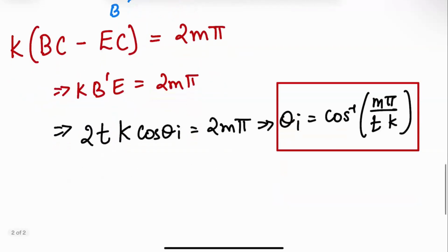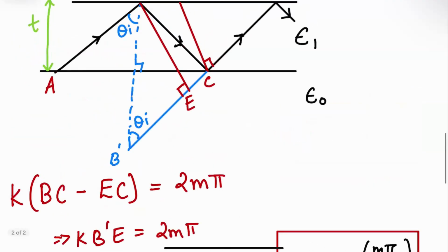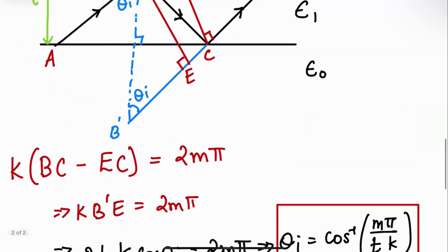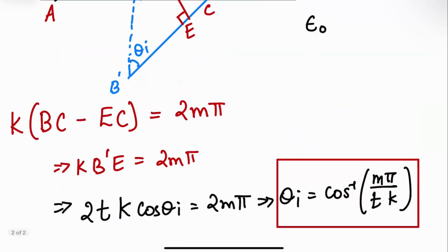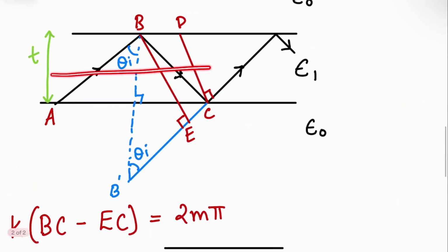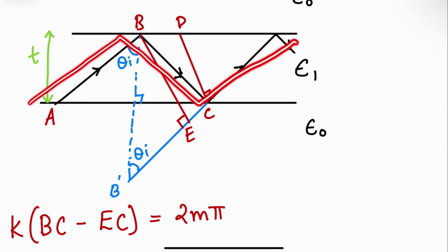So what is this saying? This is saying that the incidence angles at which I can satisfy that phase relationship, where this point is a phase advance from here or a ray advance from here, only happen at certain angles. So only these angles can support a plane wave propagation in this waveguide. If I come in at this angle, then it satisfies this phase relationship and that propagates.